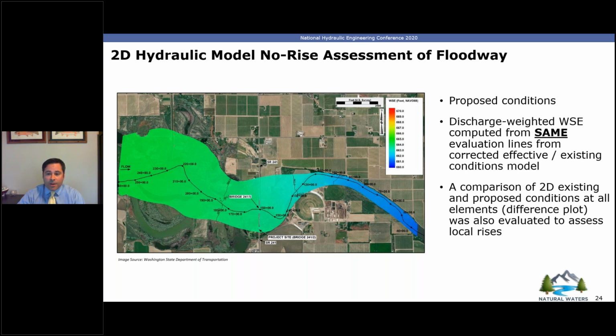Whereas if you're computing local scour at a pier, you actually may want to utilize the local velocities that occur around the pier. I will point to some great tutorials that Federal Highways and Aquaveo have put together that explain that. But please do follow up with Scott or me if there are further questions on where to extract 2D model results to use in various analyses.